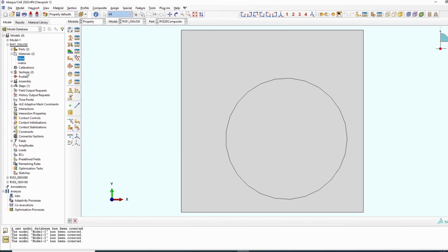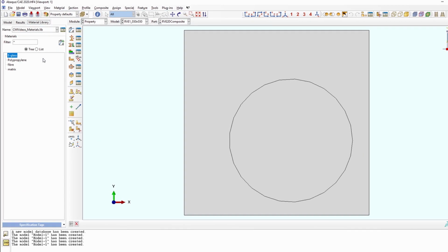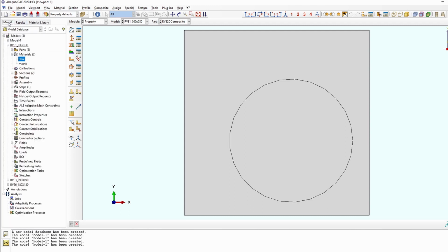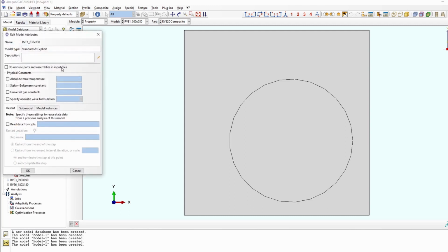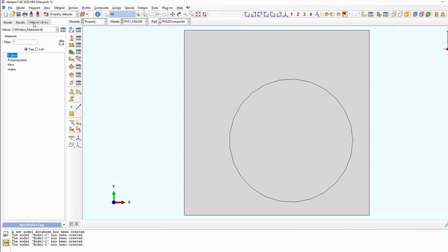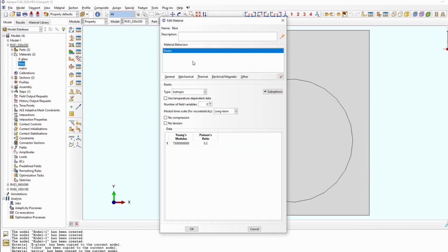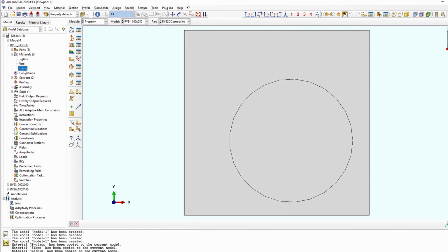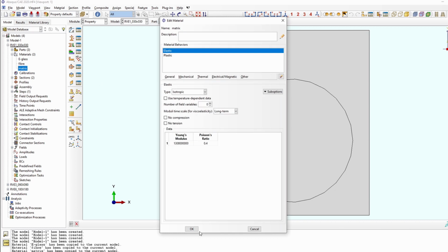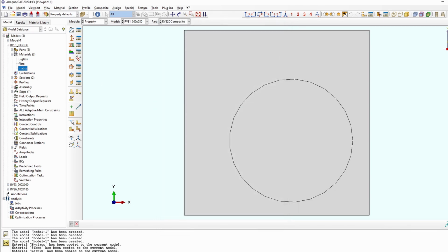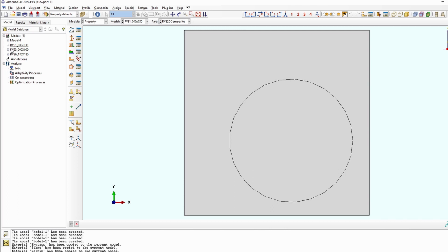But once you've added it, you do need to bring it into this environment, this particular model. So if you go to the first case, this model is open, go to its material model, add this fiber. You notice that it's already there. Add the matrix, it's already there. If we go back and check, you could see now we have the properties of the fiber and the properties of the matrix also specified. So we're not going to worry about that. This is fine.